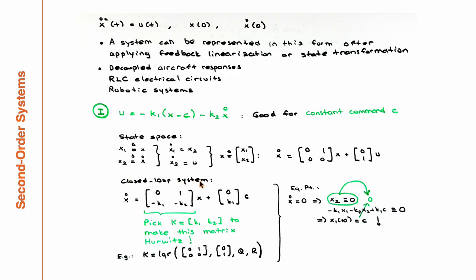So once you apply this type of a control structure and close the loop, x is x1 and x dot is x2, and I am assuming x dot is available. You can think of this as the position and this as the velocity state of my system. Like the state feedback case, all the states are available to me. If not, you can also use an observer; watch the output feedback case, a couple of videos back.